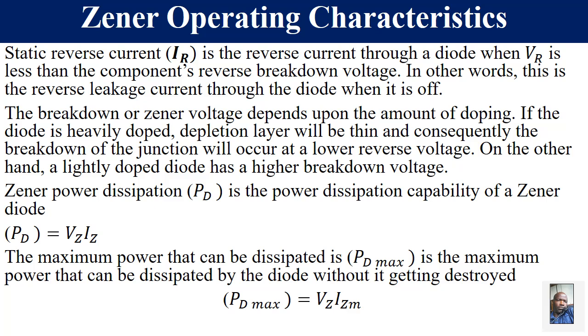Reverse voltage simply means a voltage across the Zener diode, where we mostly start from 0 and increase it in the negative direction. But when the Zener diode goes into breakdown, or starts conducting a lot of current, we say we have reached the Zener breakdown voltage of a Zener diode.